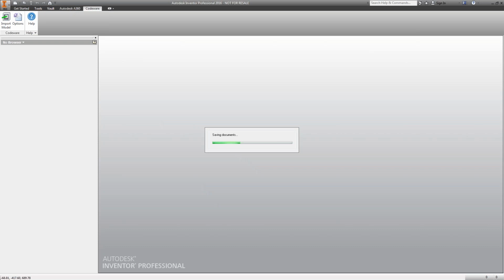So the drawings are going to be read from the solid model, and I'm going to show you this, but as you update the model, your drawings will also get updated automatically. And this actually helps a lot with the turnaround as well when you get revisions back. You don't need to go update the drawings because the dimensions will be automatically updated if you have to make adjustments to the model, things like that. So that's one of the big differences there.